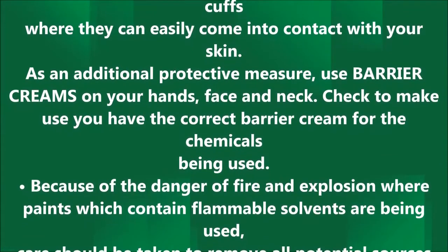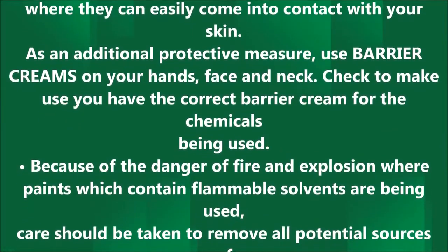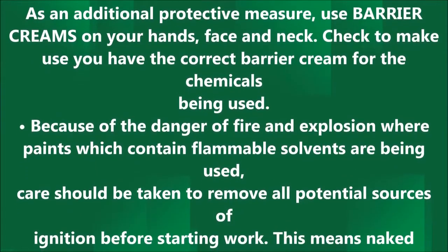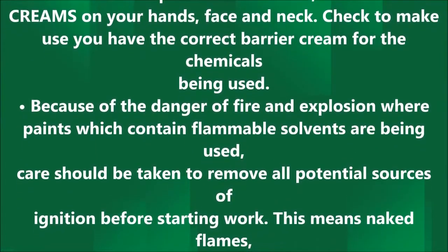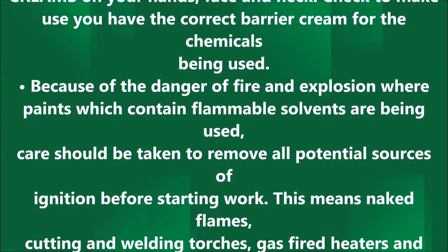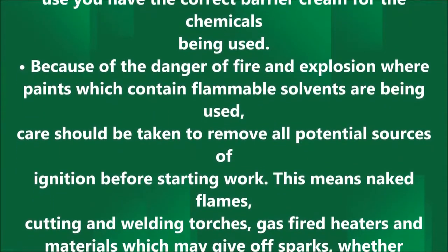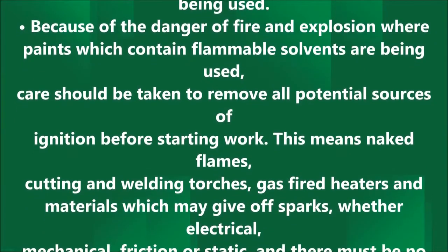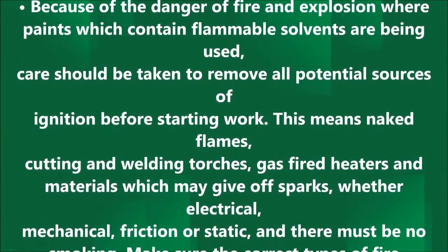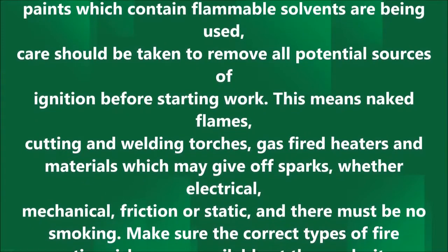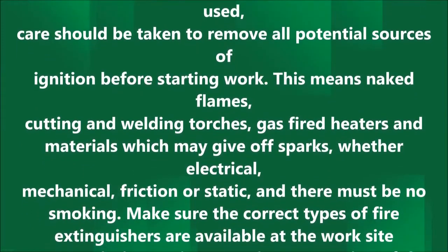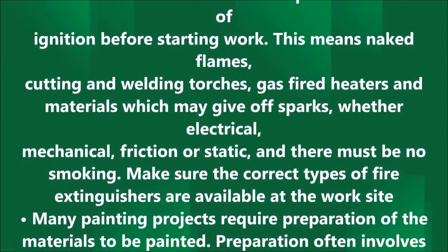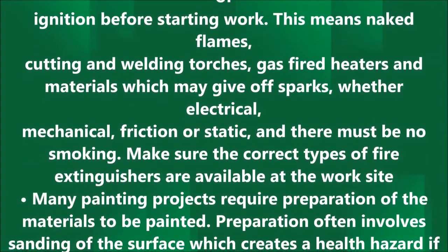Because of the danger of fire and explosion where paints which contain flammable solvents are being used, care should be taken to remove all potential sources of ignition before starting work. This means naked flames, cutting and welding torches, gas-fired heaters and materials which may give off sparks, whether electrical, mechanical, friction or static, and there must be no smoking. Make sure the correct types of fire extinguishers are available at the work site.